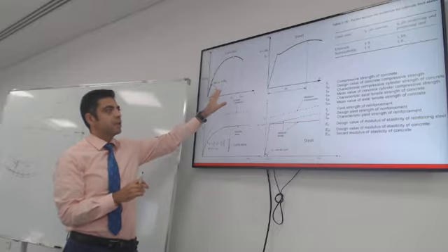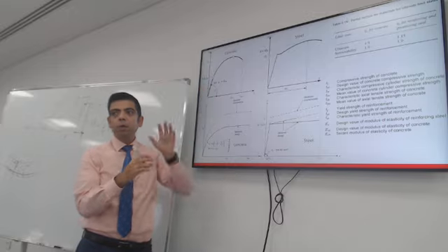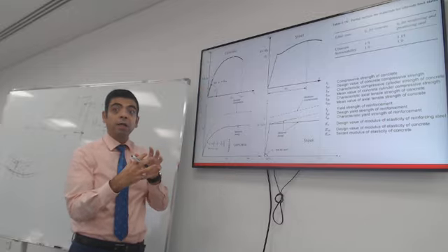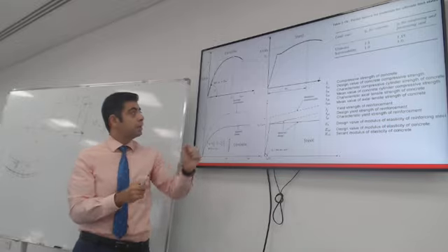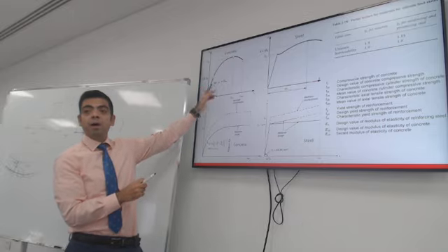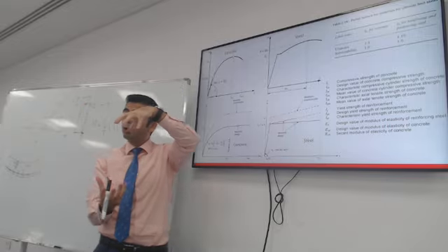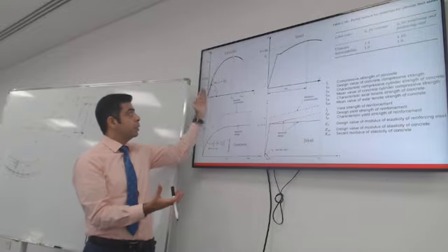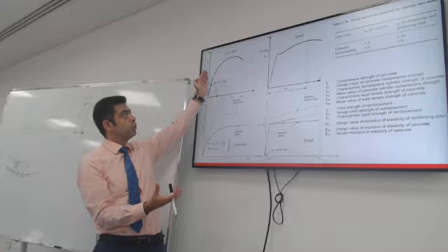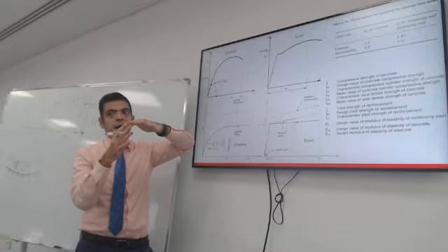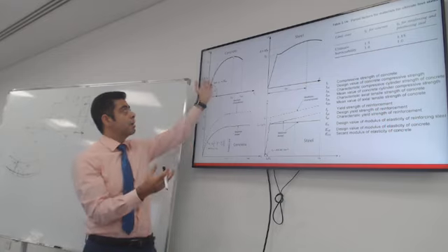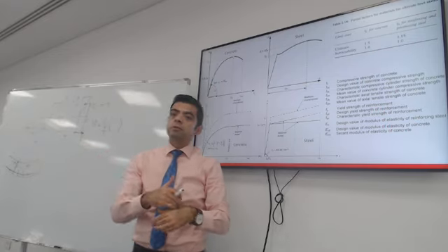Concrete is much less ductile. It will not move too much before it crushes into rubble, into dirt. This will happen if you apply a load on a cube or a cylinder of concrete. It will continue to take the load, it will continue to take the load, and then suddenly it will show cracks and it will start crushing, and it will very quickly lose the stresses.